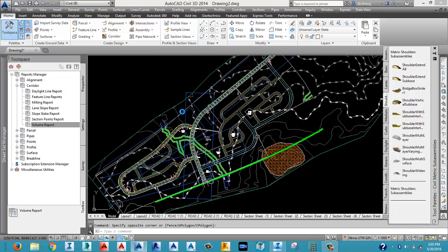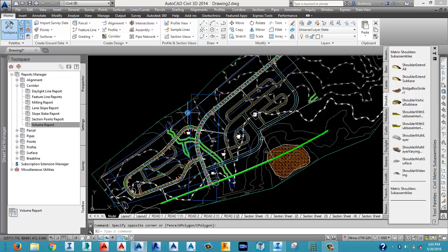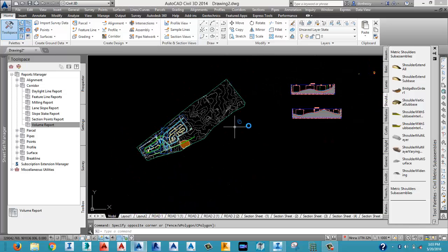So one thing is, before you get to this final stage of producing your design, you might neglect this if you do not have in mind to produce the full design. Instead of going through the stress of finishing the whole design, doing the corridor, doing the sections and so on, if you just want to do the model, finish the road alignment design, then move into your InfraWorks directly, that is always well and good.